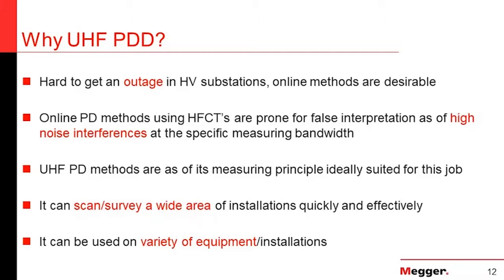And so UHF PD is one of the best tools and techniques, and we can scan a wide area with the UHF method. It's pretty much like photography of your whole site, and then you look into each photo and see what could be wrong with any of the parts or equipment. One of the other advantages of UHF PDD is that it uses a variety of sensors, either VHF, UHF, transformer plug-in, antennas, or everything. That variety of sensors gives you a good tool for scanning, checking and pinpointing every kind of partial discharge.